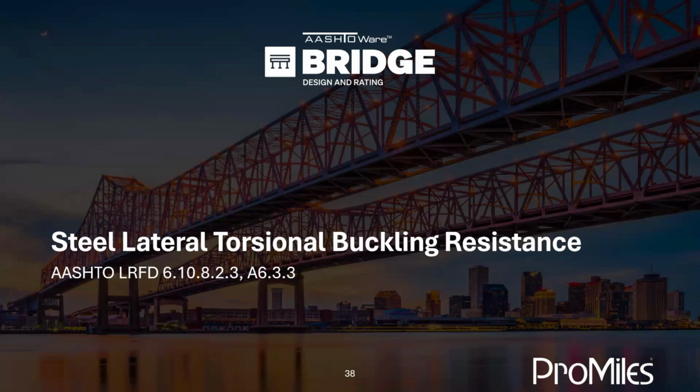Okay, as many of you are aware, there are substantial changes to how lateral torsional buckling resistance is determined with the 10th edition spec update. And this really applies broadly to all of section 6.10 of the spec, but these are the specific articles for stress and moment resistance calculations.